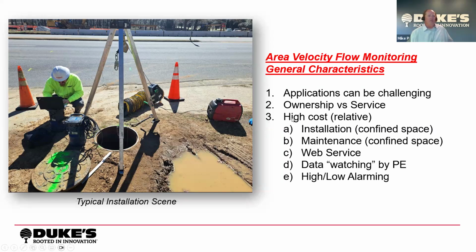So number three here, just to touch on the cost, flow data is a relatively high cost. We'll talk about level data. That data costs less, and a lot of that is around the confined space and the requirements for installation and confined space entry requirements for maintenance, of which there could be a lot. So there are those things to consider.